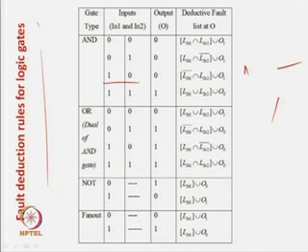Now, for 1 0 you can also see that whatever is here will be propagated, whatever is here will not be propagated. So, that is L1 intersection L2 bar, that is whatever is here will be propagated, whatever is here will not be propagated. So, any fault common between these two will also not be propagated, plus the stuck-at-1 at the output is also detectable because the output is 0. Now, the best case is 1 and 1: if both the inputs of the AND gate are 1, then what is the idea? The list over here and the list over here are all detectable, and the output is a 1.